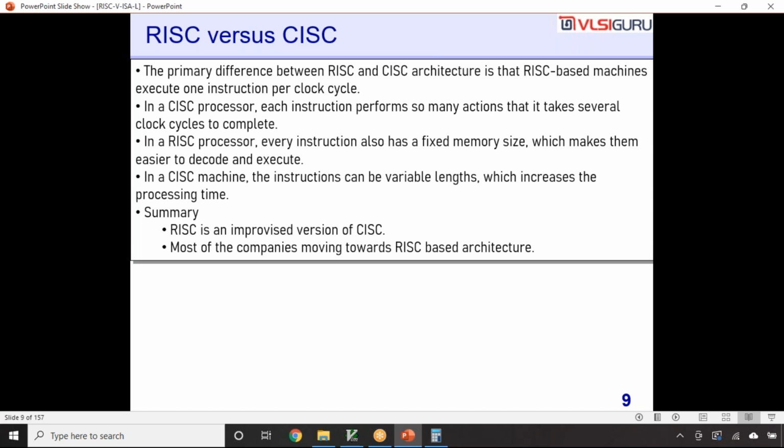Sir, sorry to interrupt. When we say the ARM RISC processors and RISC-V processor, what is the difference? Is it in the instruction sets? The instruction set is different. The way they have implemented the registers is different. The way they have implemented the internal hardware is different. The number of pipelining stages is different. The way they have implemented their arithmetic logic unit is different. All of that will be different because their hardware will be directly related to what kind of instructions they have provided. So based on that, it differs.